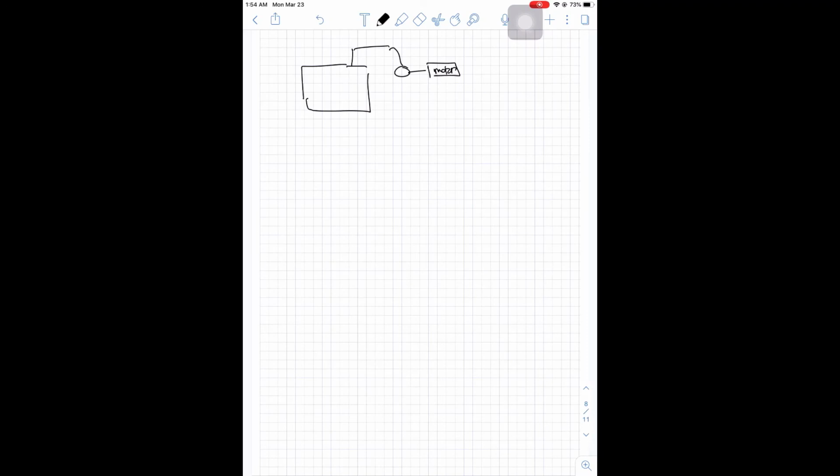If the motor speed changes with the load, whenever there are more people inside the elevator, the motor speed will go down, and the elevator will take a different time to go between floors. So in order to have the time between floors independent of the number of people riding the elevator, which represents the load, we need a motor with constant speed.